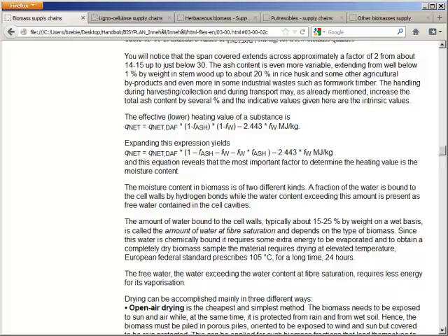Very often the logistic ashes are the same order of magnitude or even more than the intrinsic ash. So the ash composition and the ash content of the biomass as such is most often not representative of the biofuel that is finally delivered to the plant.